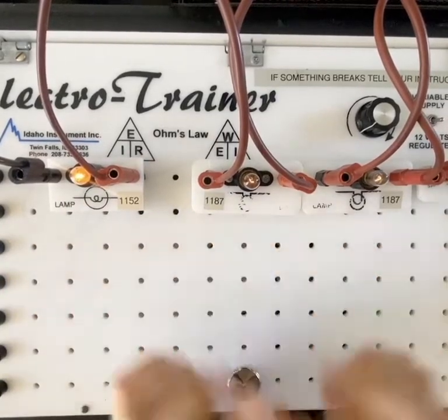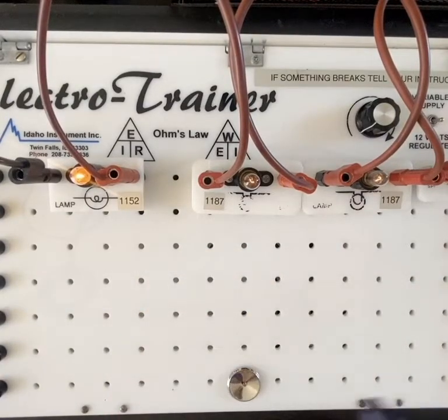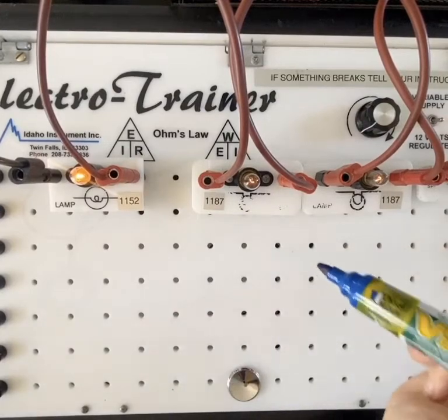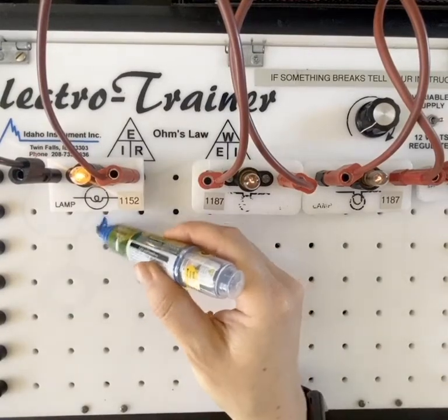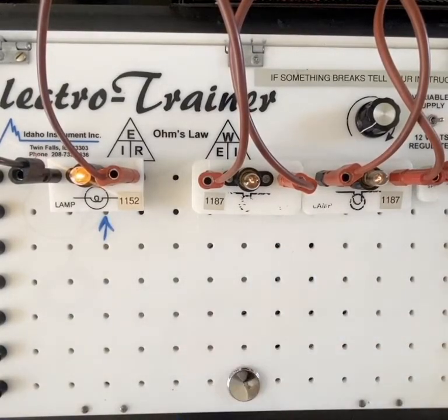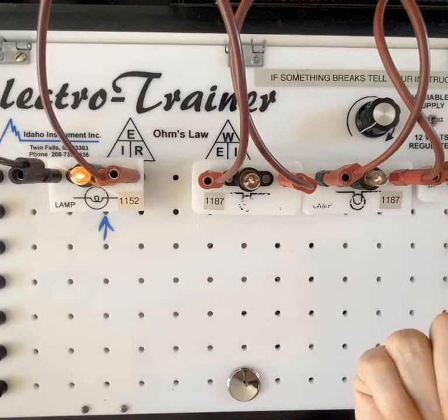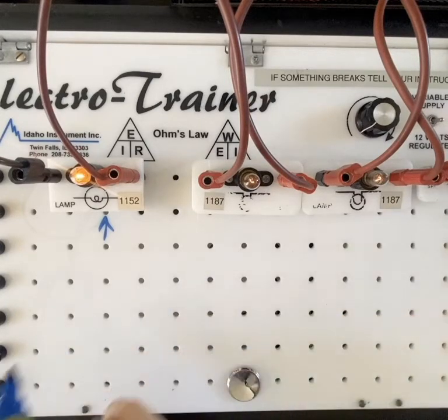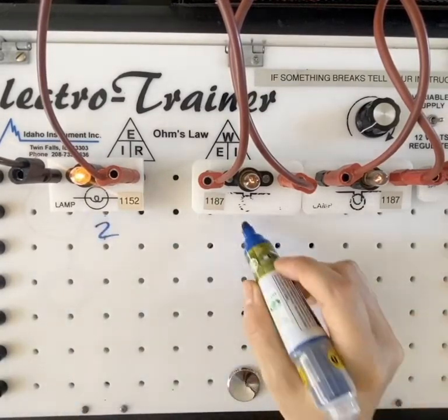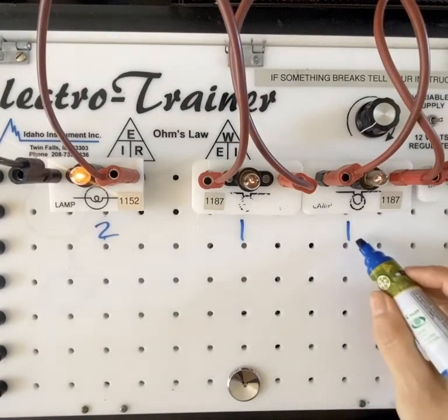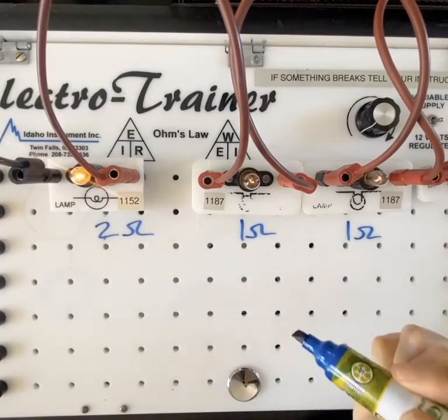Now in a series circuit, if you were to say which one's using up the most pressure, using up the most voltage, I mean, physically, we can see that this one is brighter while these ones are dimmer. So let's just throw in some arbitrary numbers. Let's just say what if this bulb was 2 ohms while each one of these were 1 ohms, kind of with what I'm saying right here. If it is going to have more resistance, math-wise, it should take up more voltage, right?